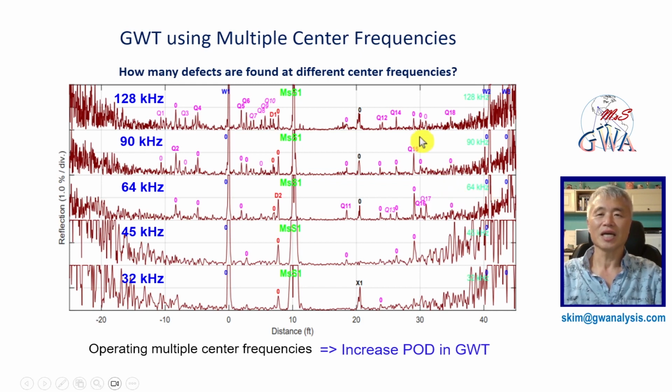In the TCG, the time-corrected gain data plot, the background noise level does not go up and go down in the middle of the pipeline. The reflected signal indicates impedance change of a pipeline that is due to corrosion defect. D1 and D2 were verified using field testing.